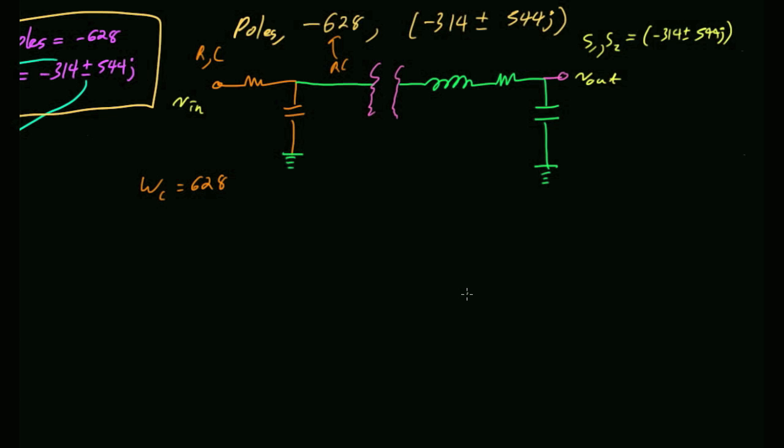The frequencies would be different because one has the inductor and one doesn't. No? I'll give you a hint. This circuit right here does exactly this. This works. This will give you that first order pole right where you anticipate it will be. This circuit will work. We can design this circuit to give you exactly those two poles.